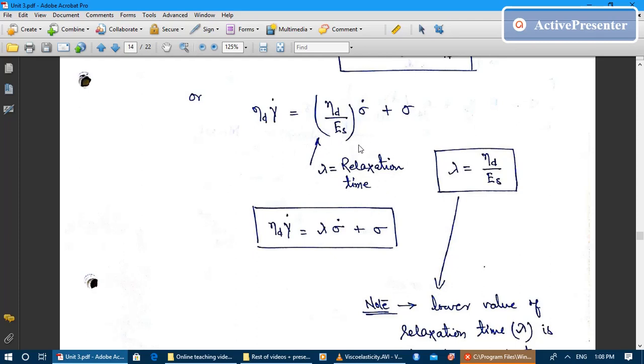Because during polymer processing we are melting the polymer and deforming it by the pressure of the extrusion machine. During deformation, the polymer will try to oppose this deformation, and relaxation time is the time after which the polymer will stop its opposition and accept the form or the shape given by the molding system.